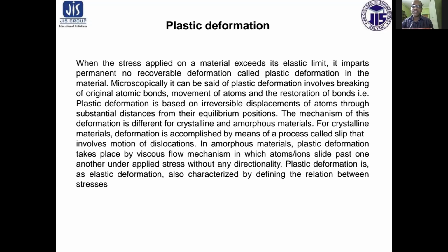Microscopically, it can be said that plastic deformation involves breaking of original atomic bonds, movement of atoms, and the restoration of bonds. That is, plastic deformation is based on irreversible displacement of atoms through substantial distances from their equilibrium position.